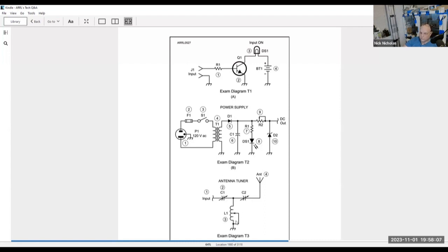Basically, you get the lowest SWR reading you can with the inductor. You move it till you get the lowest it'll get. And then you fine tune first the input and then the output capacitors. You actually go back and forth with those two until you get to the absolute lowest SWR, which is the forward to reverse power ratio. You want the most power forward, the least power going back at your radio. And that's how you use an antenna tuner.